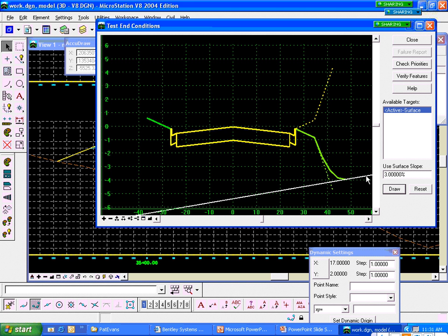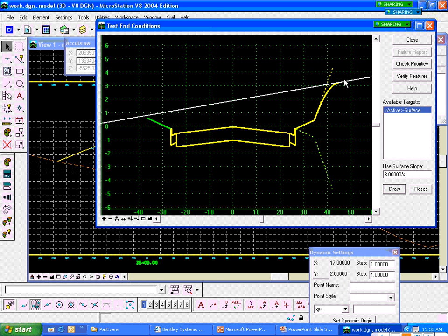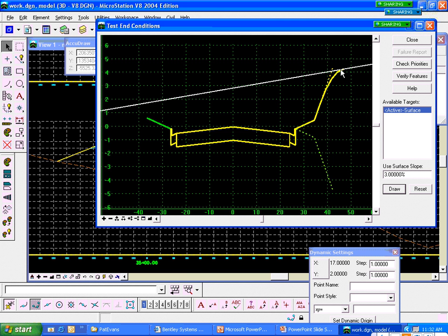But now you can see I've got slope rounding going on down here at the bottom. And then if I switch over here to a cut situation, I also have slope rounding going on in a cut situation, utilizing the different parameters that I've set up. So it's really easy to do slope rounding if you're called to do that. And it's just a click of a button now, which is great compared to how you used to have to do it.